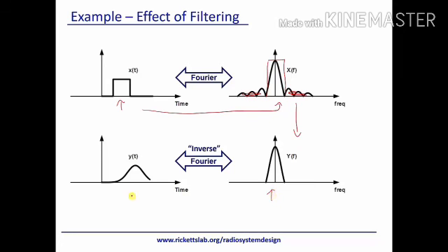But you need to remember that in the time domain it has an equivalent one, and it smooths it out. We could have actually thought about this directly in that a low pass filter is going to remove all the sharp edges and smooth things out. So here's a great example of how operating in the frequency domain here is very easy and quick, but there is an equivalent time domain change that we just need to keep in mind.